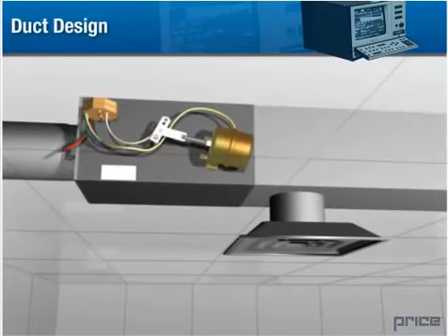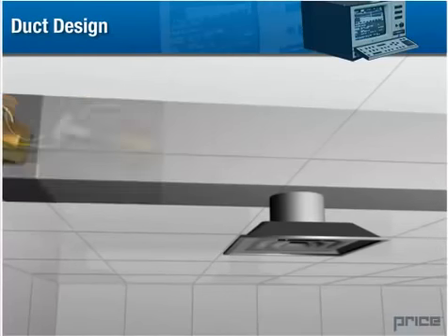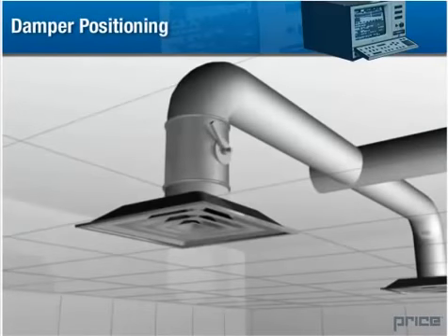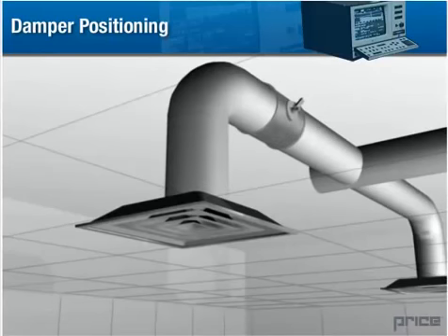Scenario 4. Poor duct design. If a diffuser is located too close to the terminal unit, damper and fan noise will be transmitted to the environment via the ductwork. It is recommended that there should be at least 3 duct diameters of distance before your first diffuser is placed. A reasonable amount of line ductwork should be used to dampen noise. Scenario 5. Damper placement. Because dampers create turbulence and noise, it is important to position them as close to the branch or takeoff as possible. The further away the damper is located from the diffuser, the better.